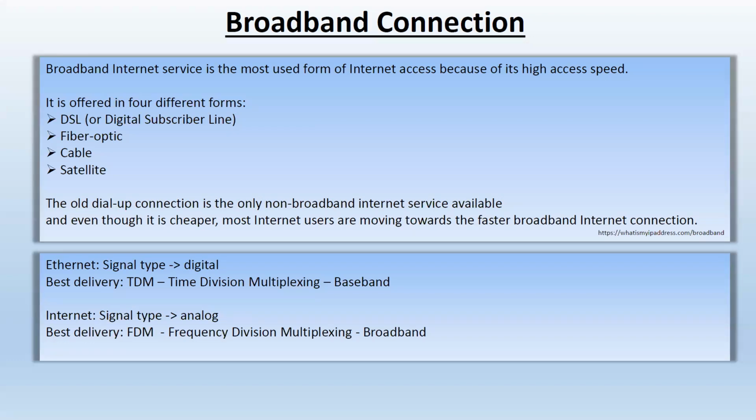The only problem was that when you picked up the phone and wanted to talk to someone, you would hear that annoying buzzing sound because of the signal from the internet. So no problem. You could get POTS filters. You would plug a filter into the telephone outlet, and then plug the telephone into the filter. It would filter out the annoying buzzing noise, and you could still use the telephone as it were. It was no difference. So if you had 2 or 3 phones in your house, you would have to plug in a filter to every single one of them, right? So you would need 3 filters.